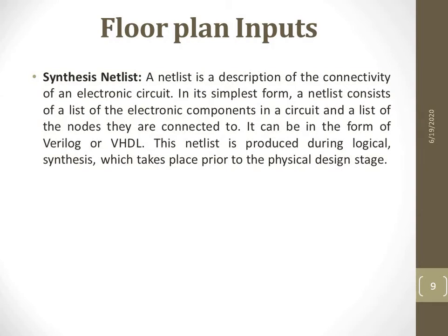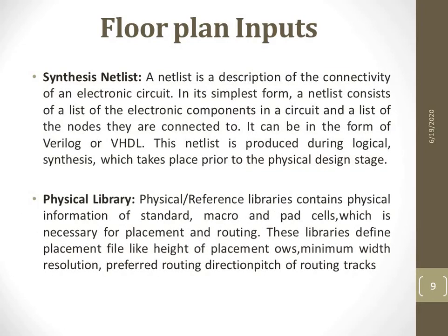A netlist is a description of the connectivity of an electronic circuit. In its simplest form, a netlist consists of a list of electronic components in a circuit and a list of the nodes they are connected to. It can be in the form of Verilog or VHDL. This netlist is produced during logical synthesis, which takes place prior to the physical design stage. For example, it is generated in the logical synthesis part.